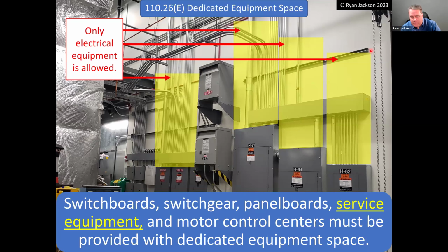very seldom we have to, but sometimes we'll have to have what we call a transformer vault. And a transformer vault is like when you have an open transformer, okay? Not a transformer in a box, just like the things you have on the pole, but they're in a building and you've got wires coming straight out of them. That oftentimes has to be installed in what we call a transformer vault. Or if you have a regular transformer, there's some criteria sometimes that says it has to be in a 1 hour room, but the exceptions in 450.13 usually get you out of that requirement. So it's really not that often that you have to have fire resistance rated construction around electrical equipment. It's very seldom.